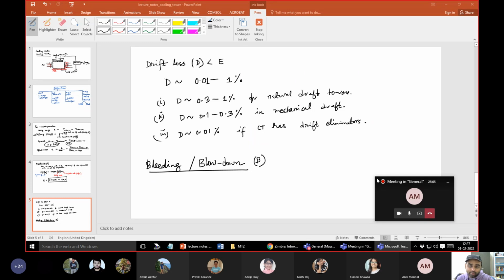To again bring it down to, let us say, 150 or 200, I have to double the volume to bring it to 150, and doubling the entire circulated water may not be a feasible solution. Right? I have to add the same amount of fresh water. So what you generally do, you bleed out, let us say, 20-30% of the water, and that you make up with the fresh water to reduce the concentration level instead of significantly increasing its volume by dilution. So you are essentially doing a dilution, right? But you are also reducing the volume and adding more makeup water, so that the net volume of the circulated water does not increase too much.